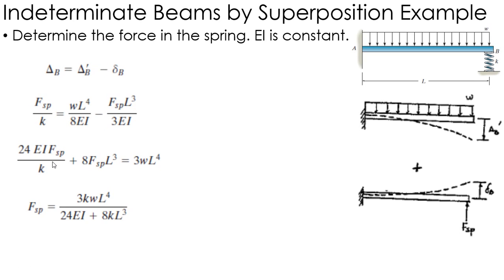and then I can solve for the force of the spring to get that. So again, I break my system up into simpler parts that I can look up in the back of the book. And then using what I know about the deflection and how it relates to the deflection of the spring, I can calculate the force of the spring using this superposition method.